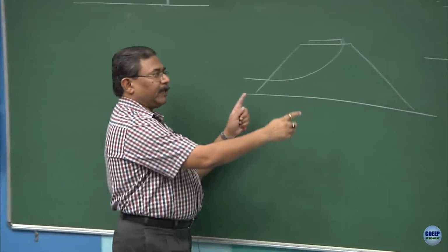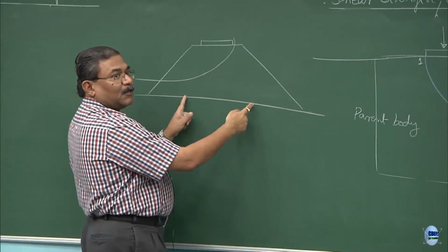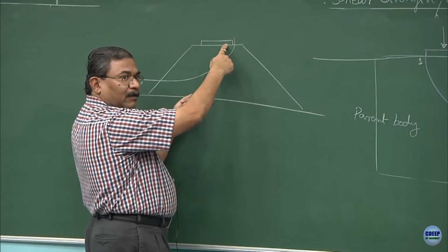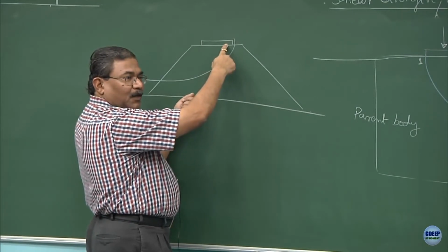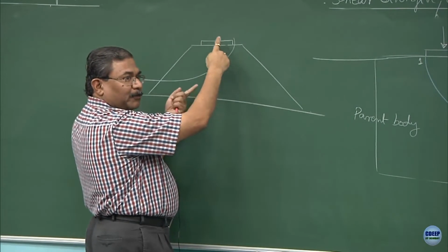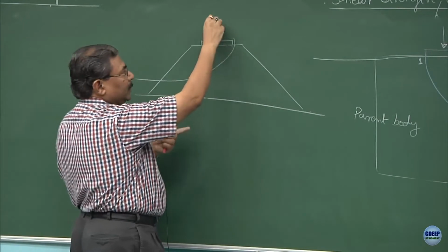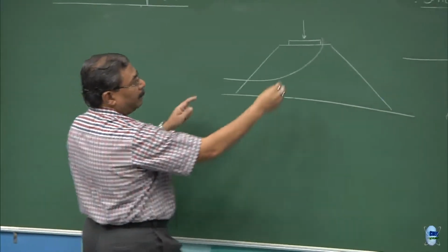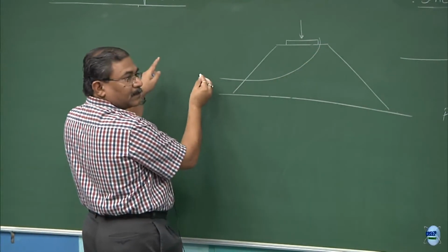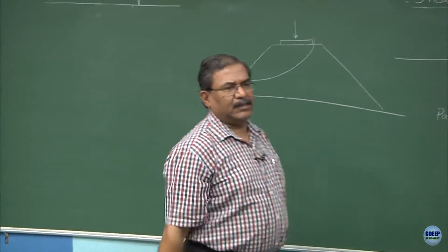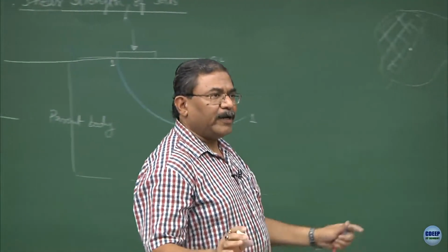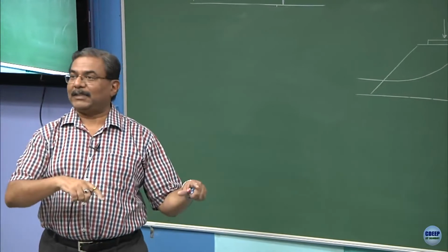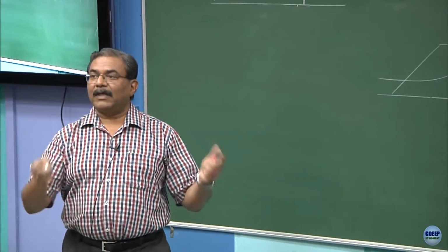You made the system very strong by compacting it, by selecting the right material so that no consolidation settlement occurs over here, very good, everything went all right. But if you do not take into account the effect of shearing of this material and the loading which is going to come on the top, the chances are the whole system may fail along this surface. You can create several of these situations now. I hope the point is clear. So let us move ahead now with the analysis of these situations, and that is what I intend to do.